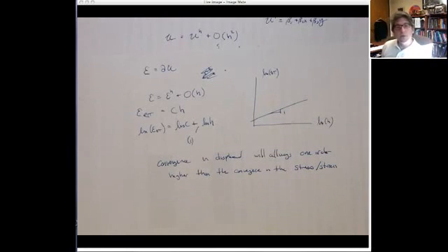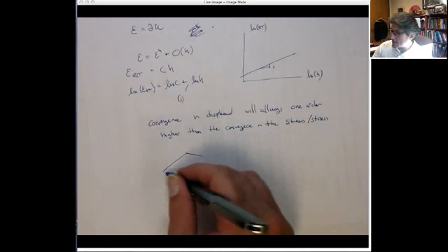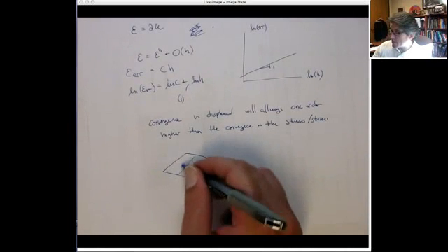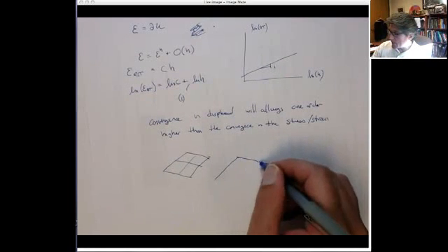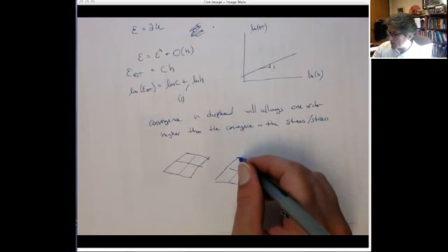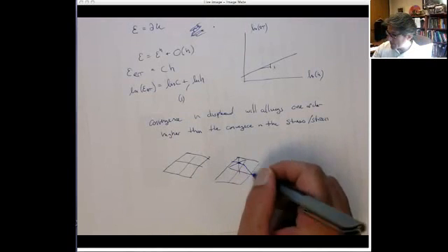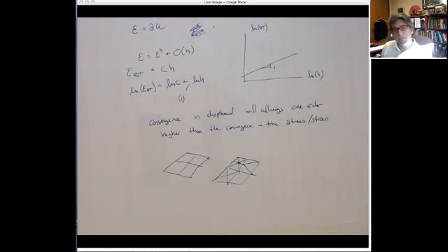So that means if you are interested in displacement results, you don't need as fine a mesh as if you're interested in stress and strain results. Okay? So when we do modal types of tests, where you're just worried about the deflection of plates, you can get away with a much coarser mesh than if I'm worried about, maybe, the stress concentrations that happen around some feature. Right there, we really need to zone in on the mesh, to have a refined mesh, okay?